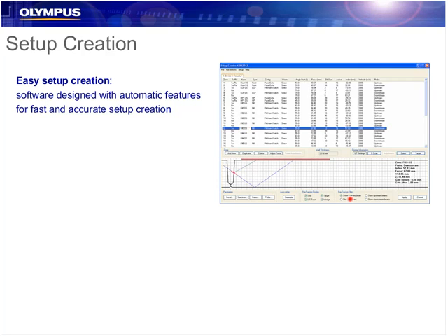And then typically for the first job, the first inspection, we would go over the cal block and maybe make some micro adjustments while being somewhat static over the reflectors and then running over it dynamically. And there's a lot of tools built in to make this very quick. So once we get in, we're able to see that the software automatically generates for us the proper beams, both on emission and where they're going to be received and the grouping of elements that are going to do so.